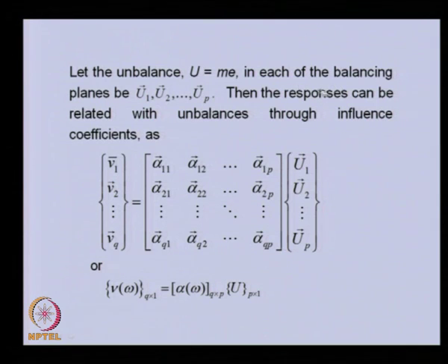Now, we are relating the response, that means the vibration of the rotor, with these unbalances through influence coefficient, as we described earlier, that we can relate the displacement and the force with the influence coefficient. This kind of thing we already discussed for the case of rigid rotor, in which these are the measuring plane locations of the response, that is Q in number.